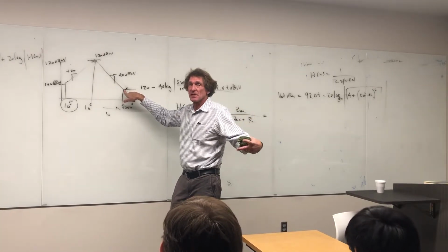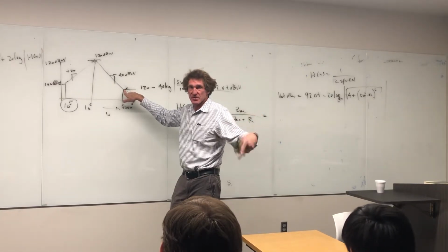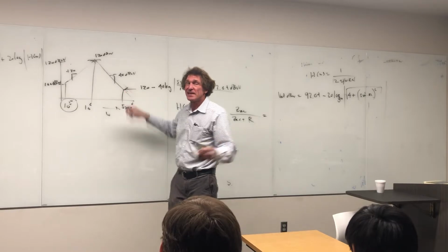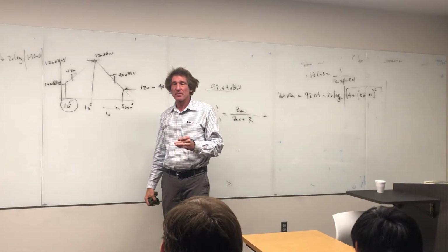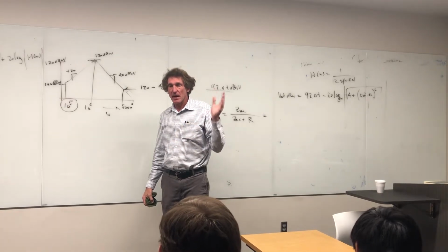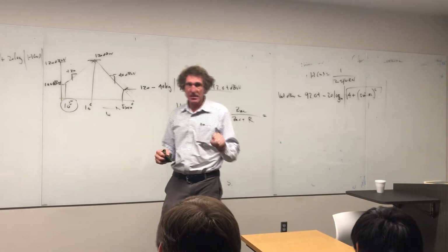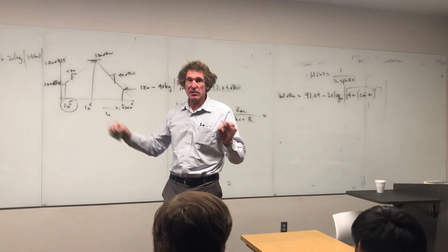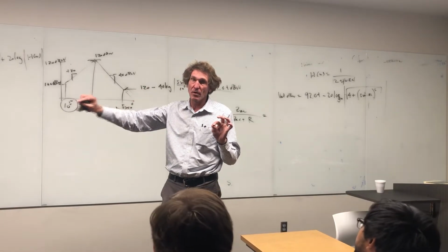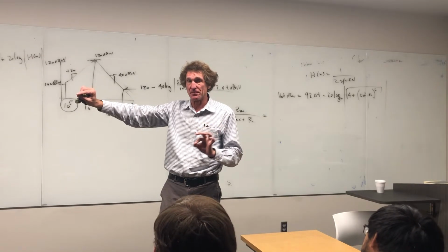If it's mil-spec, it's a lot harder to meet. Mil-spec is much harder than FCC. In Europe, it's CISPR. But really, you're always dealing in the frequency domain, almost always in dB microvolts for allowable outputs. When you get something like a laptop or a tablet, there are things called conducted emissions. It means when that thing gets plugged into a charger plugged into the wall, anything that goes right through that direct connection to the wall is a conducted emission.